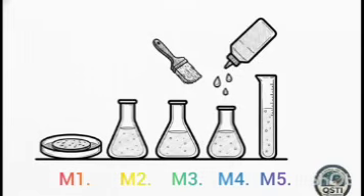greater than 10 micrometers. Container 3 is the acetone rinse of the Cyclone I outlet and the Cyclone IV inlet, giving us that middle ground particulate between 10 and 2.5 micrometers. Then we have Container 4, which is the acetone rinse of the Cyclone IV outlet and filter housing. That gives us the rest of the PM2.5 catch that just didn't quite make it onto the filter paper. And finally, Container 5 captures the cold impinger water for your moisture calculations. You're using specific nylon or fluoropolymer brushes and acetone here to make sure every single microgram of particulate is quantitatively transferred without any outside contamination creeping in.